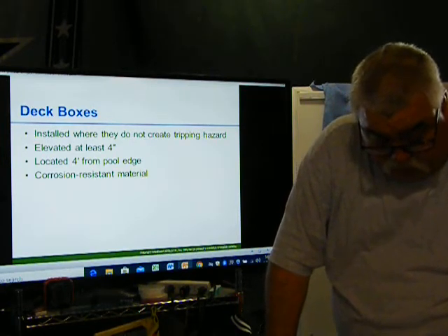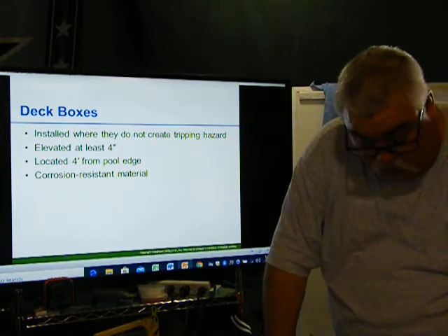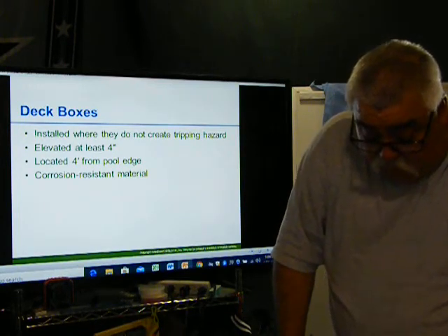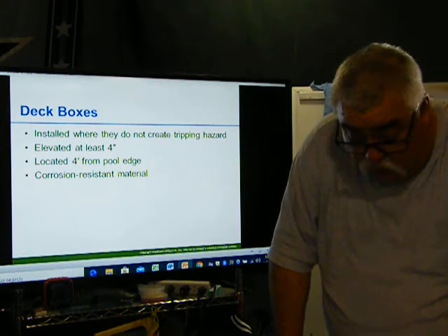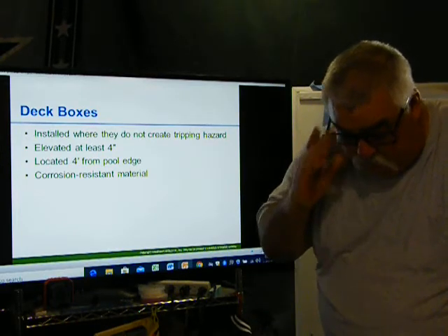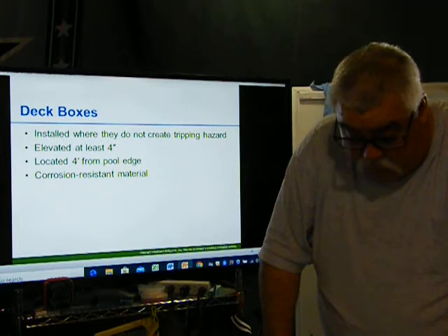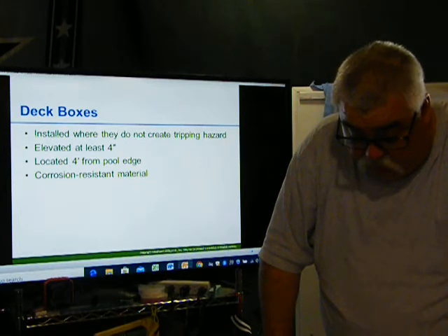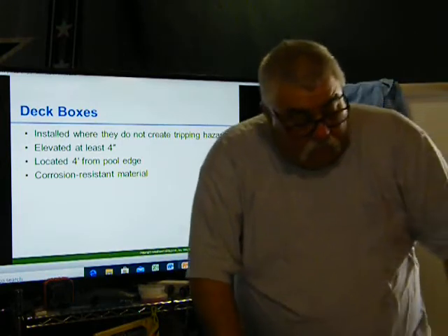The flush deck box can be used for lighting operations at 15 volts or less, if it is sealed and potted. Other provisions and requirements concern the installation of deck boxes, as well as boxes used to house GFCIs and transformers around pools, and are found in section 680.24. Also, further specific information and suggestions should be obtained from the utility company and the local inspection authority.